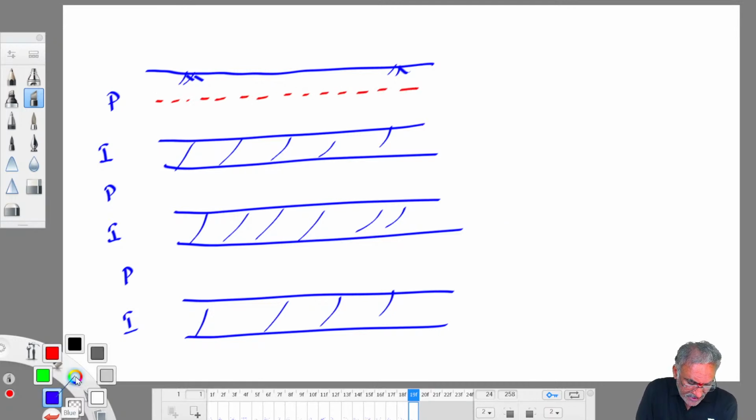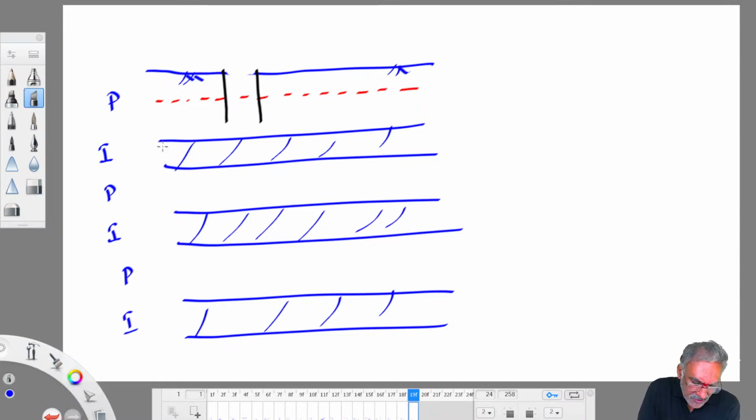A shallow open well is dug at shallow depth. So it is not depth, sorry. This is a shallow open well, which collects water from the top pervious strata. This is the aquifer. Here groundwater is there. So from here it collects water. This water rushes into this well. This is called a shallow open well.